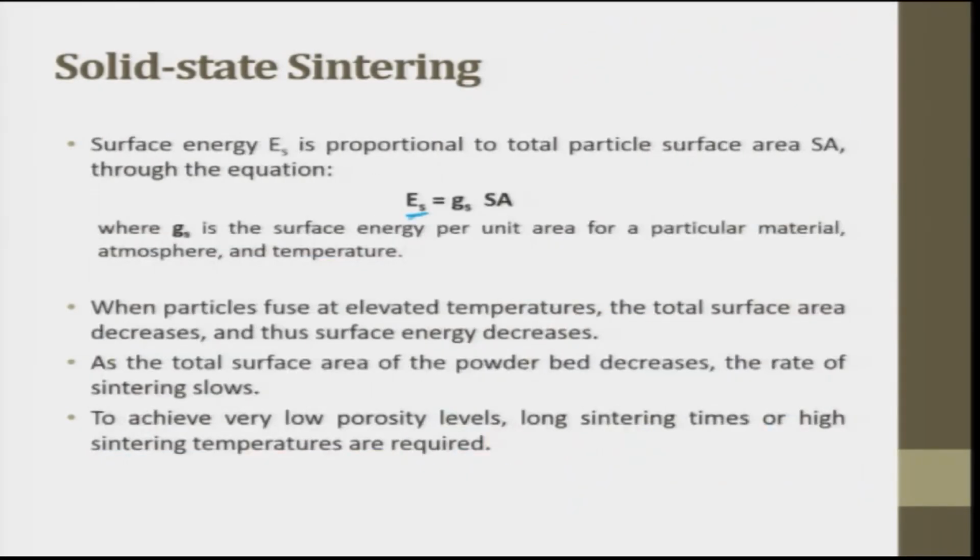The surface energy, so you can see here free energy ES. The surface energy ES is proportional to the total particle surface area SA through the equation ES is equal to GS into SA, where GS is the surface energy per unit area for a particular material, atmosphere and temperature. So, this is a star. When particles fuse at elevated temperatures, the total surface area decreases and thus surface energy also decreases.